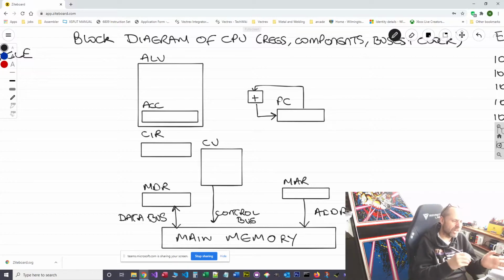We tend to not show that, but you'll see it on big, nice block diagrams. The data bus is drawn as big fat arrows joining all the registers together. So it issues these latch and enable commands to different components within the CPU using the control bus.